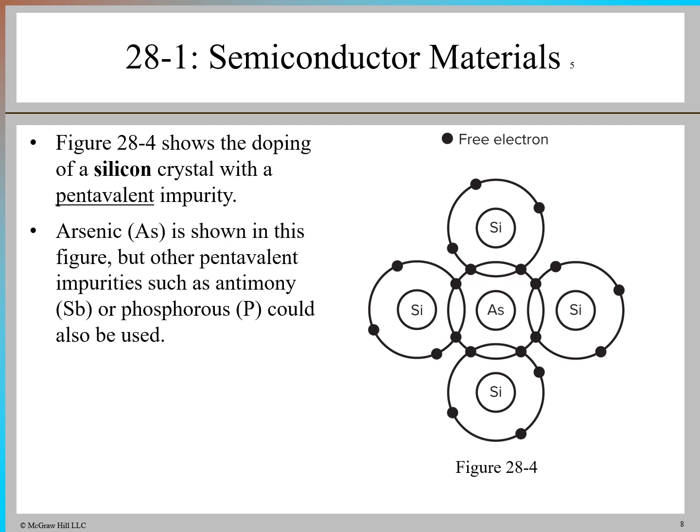This type of material is called an N-type semiconductor, where free electrons are the majority charge carriers. Even though the material is neutral overall, the doping creates some positive ions that are fixed in place. There are also a few holes or vacancies left by missing electrons, created in the material due to thermal energy. The free electrons are attracted to these holes and fill them, making the holes act like positive charges. In N-type semiconductors, free electrons are the majority current carriers, and holes are the minority current carriers.